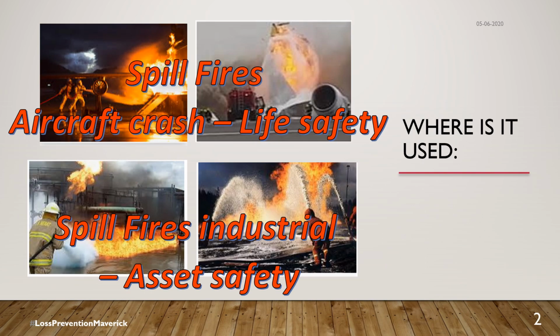Now, where can the firefighting foam be used? As the name suggests, it is for fighting fires, of course. It can be used for spill fires created during aircraft crashes and also for industrial spill fires. The difference, however, is that for aircraft crash, it's primarily life safety. So the foam should be a rapid knockdown and therefore give time for personnel to escape. Whereas for industrial spill fires, it is to avoid the escalations and primarily concentrated on asset safety.